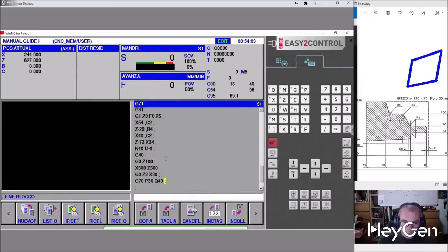When we're inside, even if we know we're already out, we always come back first in X200 Z300 and then proceed with M5 and M30 insert. It is important to remember that if you forget M5, M30 will exclude it, which could lead to errors. Additionally, if you forget M9, which is the coolant shutoff, not all machines will exclude M30, potentially causing issues.